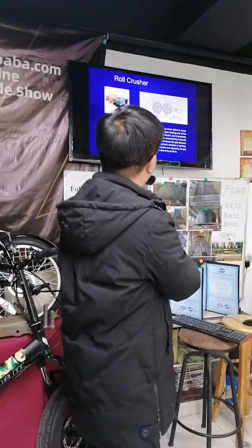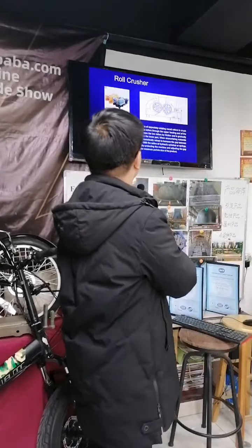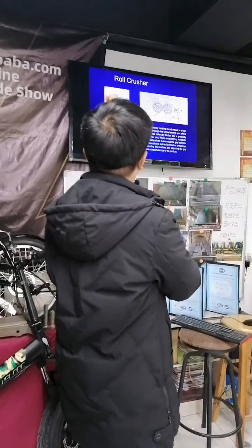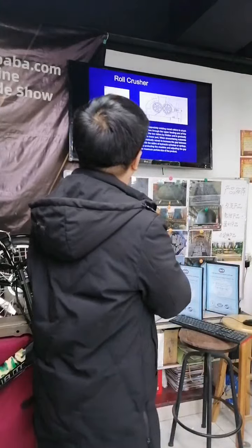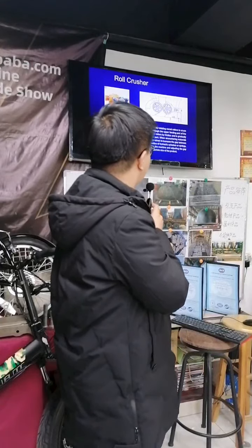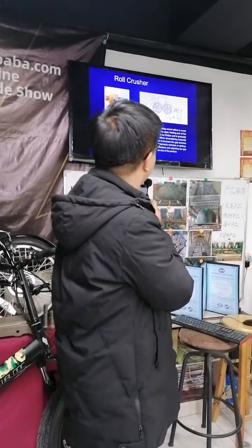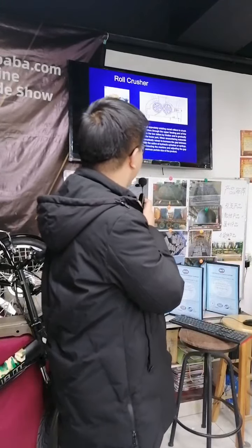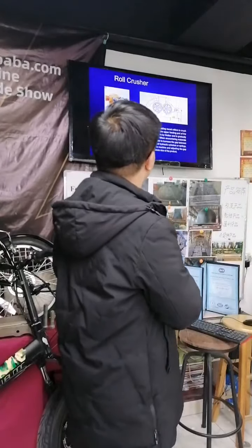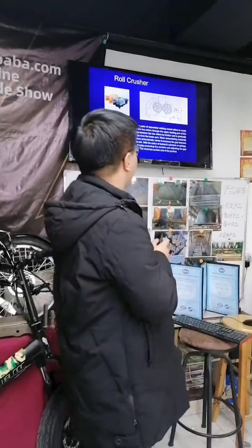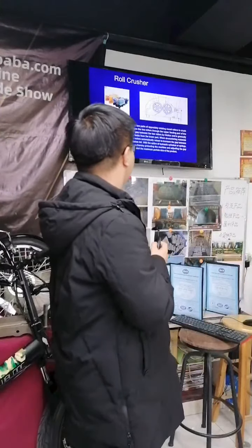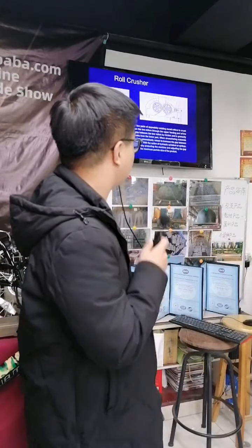When encountering materials that are too hard to be broken, the rollers retract to increase the gap between the rollers, and the over-hard materials fall. With the action of the hydraulic cylinders or springs, the rollers return to the original gap, thereby protecting the machine. Adjusting the gap between the two rollers, you can control the particle size of the product.